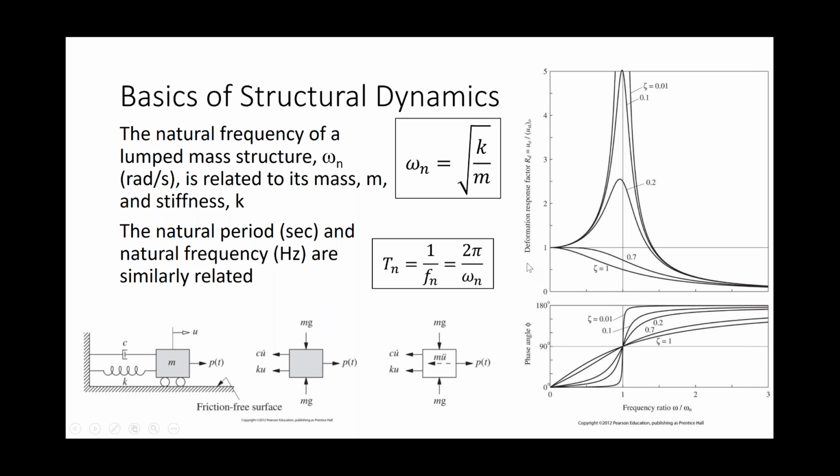One of the things that most people have encountered is that when you oscillate a structure, or you vibrate a structure, if you happen to vibrate it at its natural frequency, you get very large oscillations. So many of us have seen Tacoma Narrows videos, which has something to do with this, but there's a whole lot more involved there. But the idea being that if you force a structure at a frequency omega and it has a natural frequency omega n, if the forcing frequency and the natural frequency of the structure match, you get very high amplitudes. You get dynamic amplification.